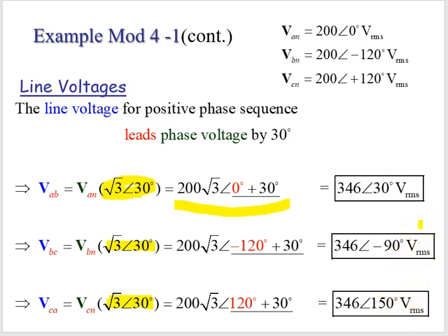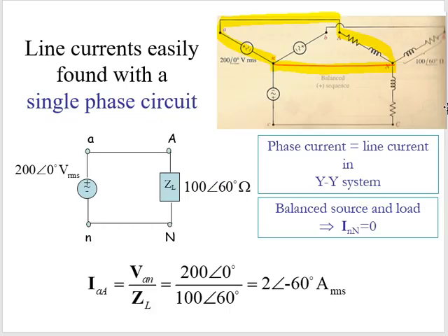So for our phase voltages, we would say our phase voltage, VP, is equal to 200 V RMS, and that's just a magnitude. Now we have our line voltage, VL, is equal to 346 V RMS, where we're using the RMS subscript, even though we know in power RMS is a given, we're using that to make that clear.